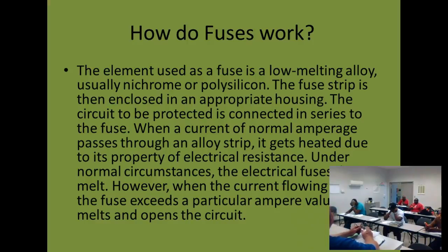So, y'all, that means infinite. That means your meter's not strong enough to send a voltage across the air to the other lead, right? Some of you probably have auto range on these meters, or you might be able to select a scale, a higher number than a lower number. And this is not a math class. They do go by the metric scale. They'll throw K out on you and M out on you, right?